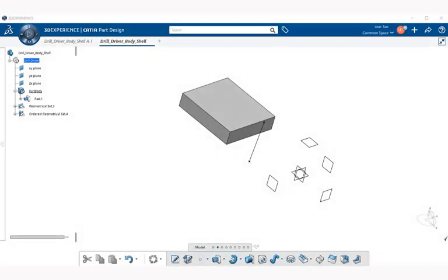Geometrical sets. The simplest way to think about a geometrical set is as a container for features. What is meant by a container is that it's a place you can organize information pertinent to the design as well as its intent of the part you are modeling. Being that 3DEXPERIENCE is very flexible in what it allows the end user to do, the only steadfast rule about geometrical sets is that they cannot contain solid features, that is, items created in the Part Design application.